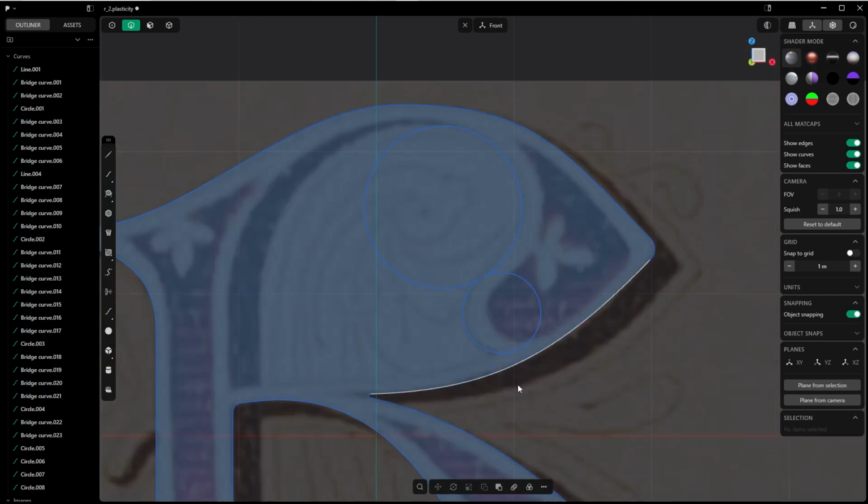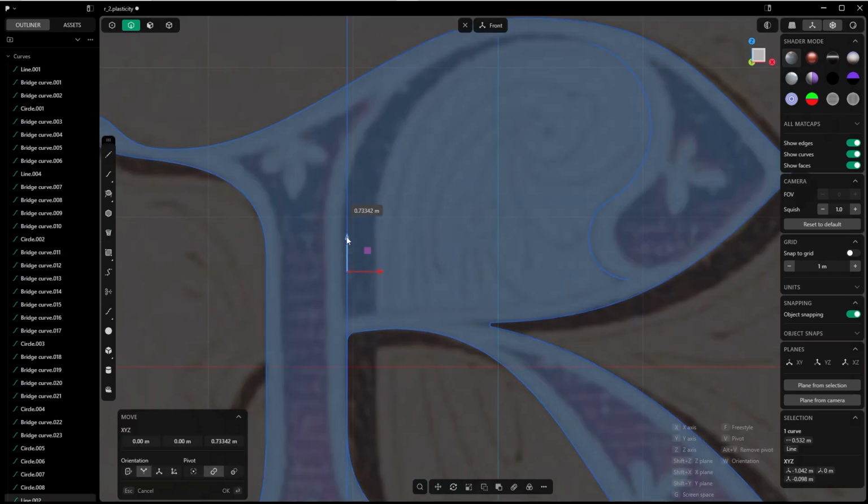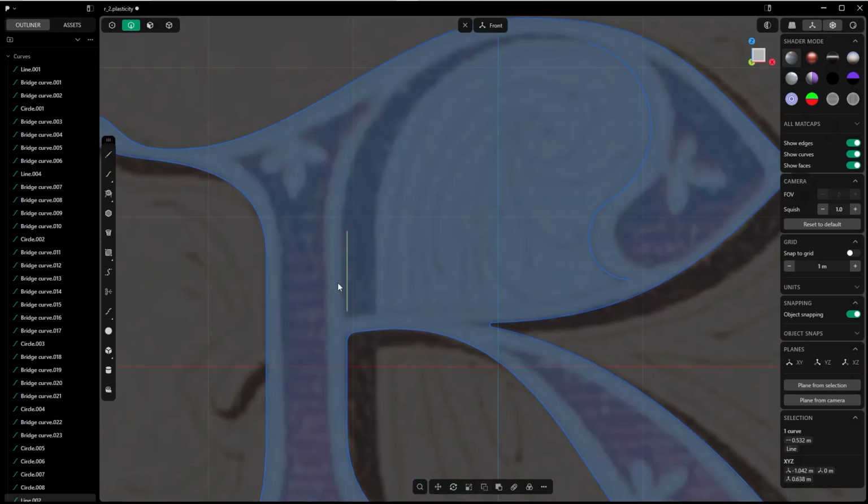Now let's trim this part, creating a simple line here. Okay, and let's press T. And let's make a similar thing here at the top. Shift A, somewhere here. Okay, perfect. So let's delete this line and trim this part, pressing T. So that's what I wanted, this perfect curvature here. Now we can try something crazy. Duplicate this line. So we have a perfect straight line here. And the fact that here is a deviation, or you know what? I will create a spline curve.